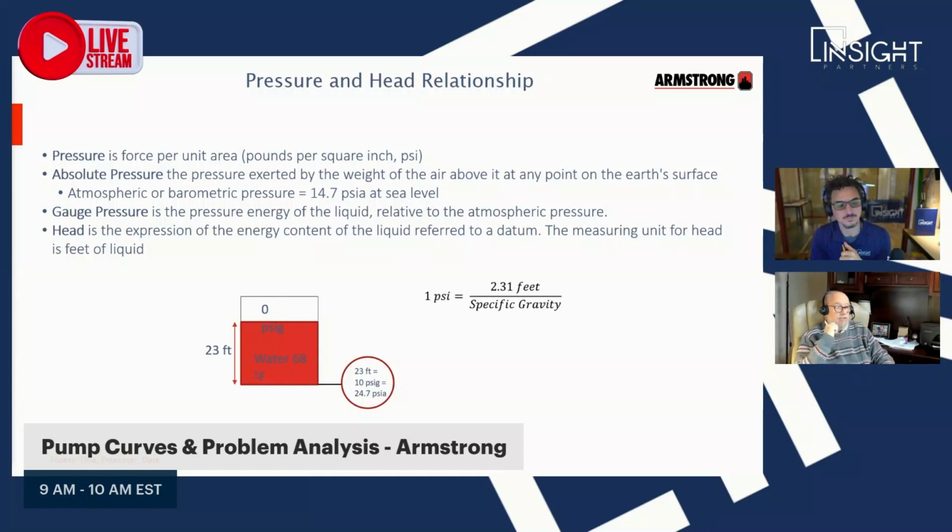Yes, it is. It is not pleasant to fix, and I really hate to be the guy to tell you that. When I talk to engineers, because a lot of my job I spend working with engineers, helping to figure out why their system isn't doing what they thought it was going to do. Adding more pumping power is not easy in the field, especially cooling. It's just not that easy. And it gets worse when we have to start changing motor sizes, bumping from 40 to 50 horsepower motors, and we have to change the drives and VFDs. It gets ugly. So I like to avoid that at all costs because it's just not fun.